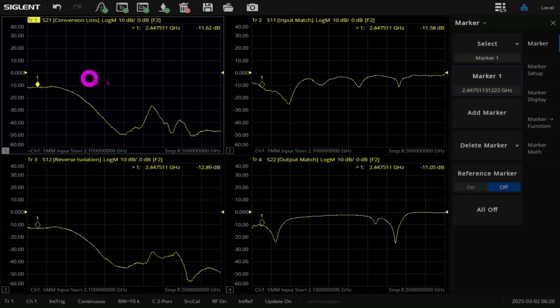First of all, the conversion loss of the mixer is around -11 dB, which happens to match almost perfectly with its data sheet. And if you look at low IF frequency, so here, for example, at 2.1 gigahertz or so, that's an IF of 100 megahertz, because our LO is fixed at 2 gigahertz. You can see the conversion gain is flat up to a certain frequency, and then it begins to roll off. So around, let's say, over here or so, we have our 3 dB point. So this mixer at 3.5 gigahertz is already running at an IF of 1.5 gigahertz, and that's basically the bandwidth of the IF port of this mixer, and that's exactly what the datasheet says.